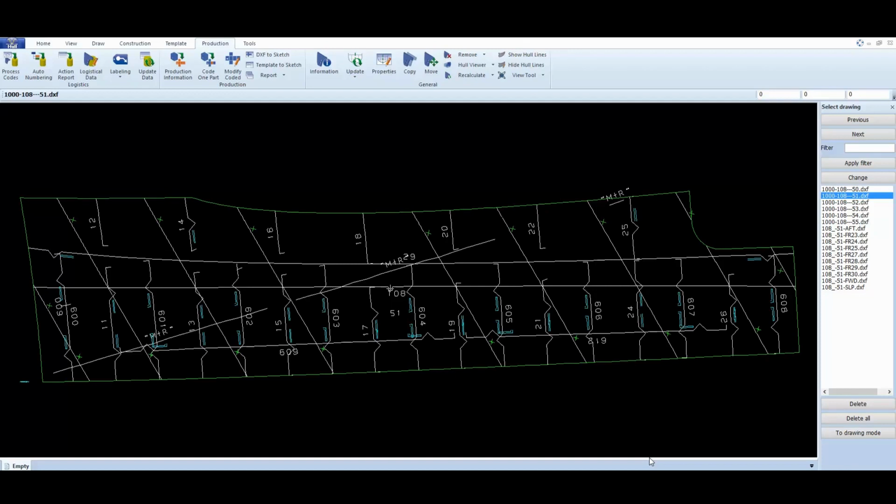There are 3 steps when calculating the optimal jig pillar heights. The first one is to create an optimal jig plane from the 3D model for the larger shell plate panels. The second one is to create a pinching drawing where the calculated height of the pins will be displayed and where we will also see the regular marking lines and the shell plate numbers. The third step is to calculate the optimized position of the pin jig and display them in the view.